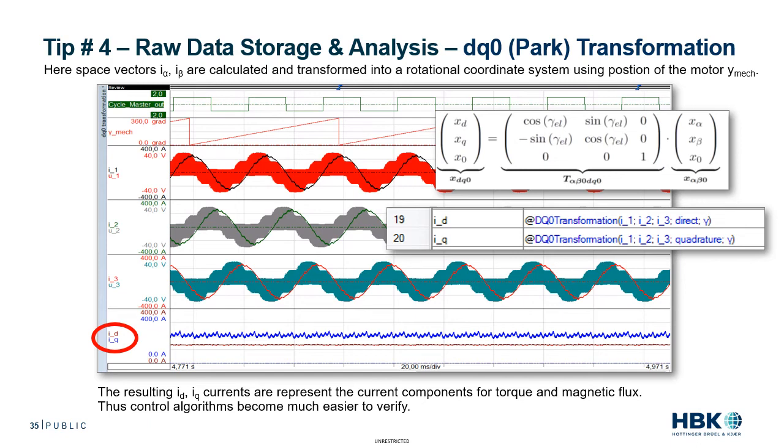Actually, inverters think in DQ0 entities, since this is what they compute. So basically, this allows you to compare the calculated DQ0 control measurements from the power analyzer, which can be streamed to your dyno, and compared to your inverter's DQ0 control measurements. This helps engineers developing inverter firmware understand how well their inverter works with the motor, and maybe decide they need to change the firmware to achieve better results to improve the efficiency, especially during control changes.